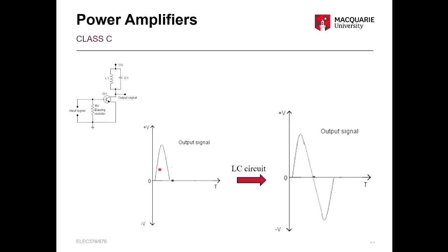But of course, this information is all sort of just replicated from here. So this is reliant on your signal being something like RF transmission, where you have a carrier frequency, which you know and you can tune to. And then you can recreate the signal here, and you get much better power efficiency. So we won't go into the details of those, but just so you know they exist and the kind of applications that you might want to use a Class C amplifier.